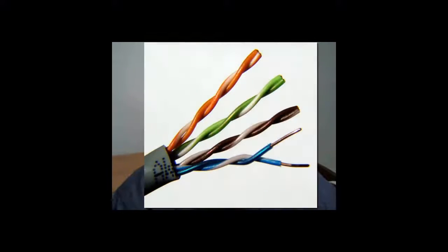My friend Tim, who I mentioned of cables and connectors, has a great description. He says that it's like tying a t-shirt up in tight knots and then dipping it into dye when we tie-dye it. The dye, like the radio interference, can't get into the knotted places. Same idea in a twisted cable. So the solution, to carry faster data, was that they twisted each pair a different amount. Now the twists were tighter, and the pairs never met at regular intervals in regular places like in the Cat3 cable. So the problem was solved.